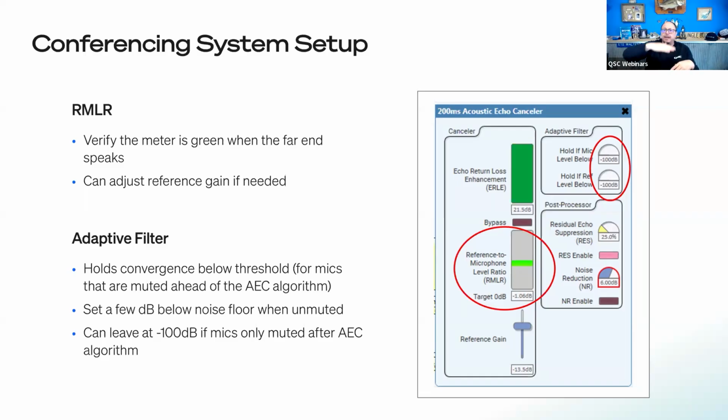And when they're talking, that should be hovering right around that green area there. So if you have multiple microphones in the design, set it so that you'll increase in one AEC a shared AEC gain reference. You'll bring that gain in, and then you'll use these reference gains below it to adjust so that they're all right at that 0 level or that mid level there.